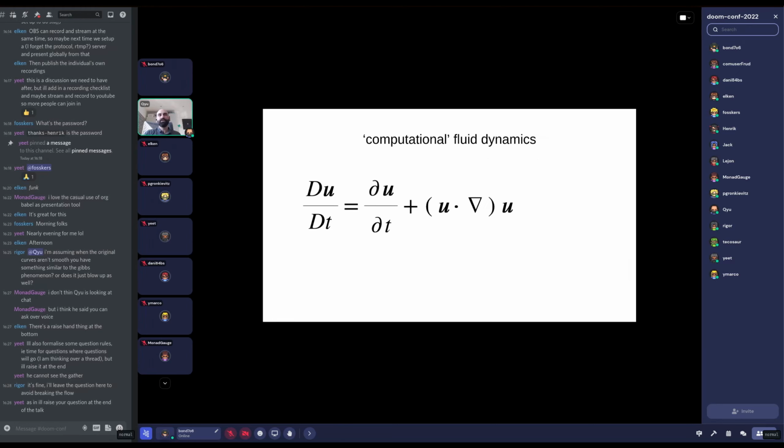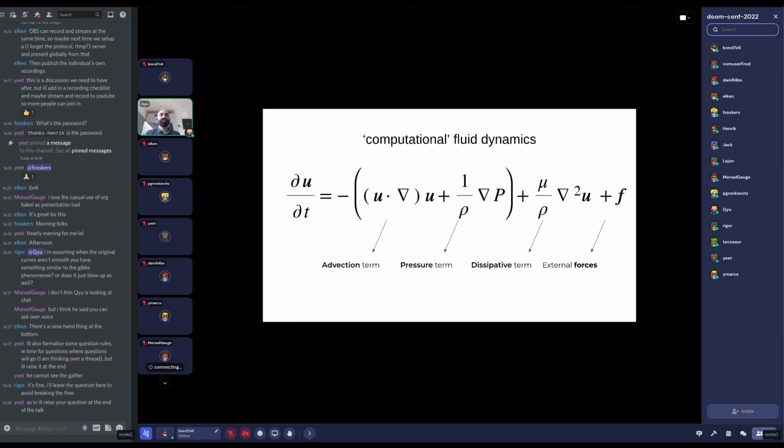And similarly, we introduced something else which was called the material derivative. And this material derivative, or Lagrangian derivative, again, gets decomposed into a partial derivative with time and another partial derivative, again, related to space. This is a quite complicated term, an advection term. We won't break that down because we don't want to do too much multivariable calculus. But essentially, this gives us this form of the Navier-Stokes equations, or at least the momentum conservation part of the Navier-Stokes equations, which we can think of in several ways. So this is this term here.